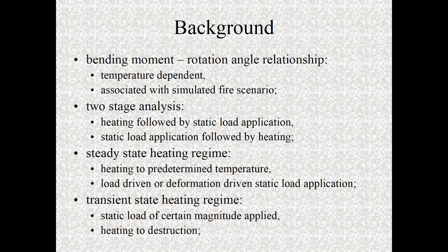The bending moment rotation angle relationship is temperature dependent and its evolution in real fire is dependent on actual fire development. This in turn depends on many factors which are of random nature and beyond our control. Thus, two bounding scenarios have been selected for application, the steady state and transient state heating regimes.